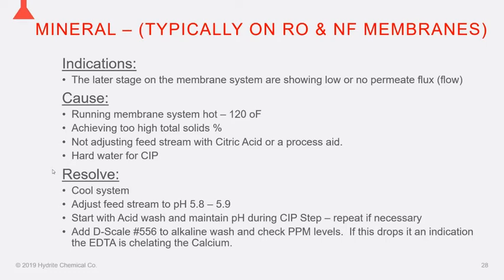So causes: running very hot, trying to achieve too high of solids, or trying to do so without adjusting the pH in order to hold those minerals in solution. Ironically, another cause can be CIP. If we're using improper water that's really high in mineral, that can actually cause a collection of mineral over time that fouls the membranes out.